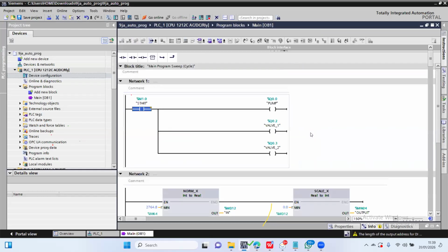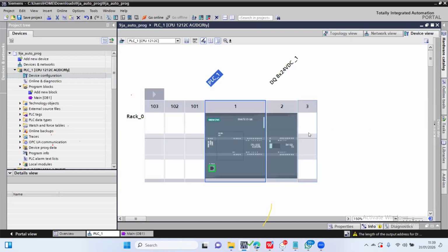So these are part of the things that would make you a good engineer. You need to know exactly what you are trying to design. So here now, if I only need limited expansion, I can buy 1211, which has no expansion, 1212 is limited expansion with only 2 slots. Then 1214, you start from 8 expansion slots. Then you can go 1215, 1217. That gives you more IOs on the embedded PLC itself.